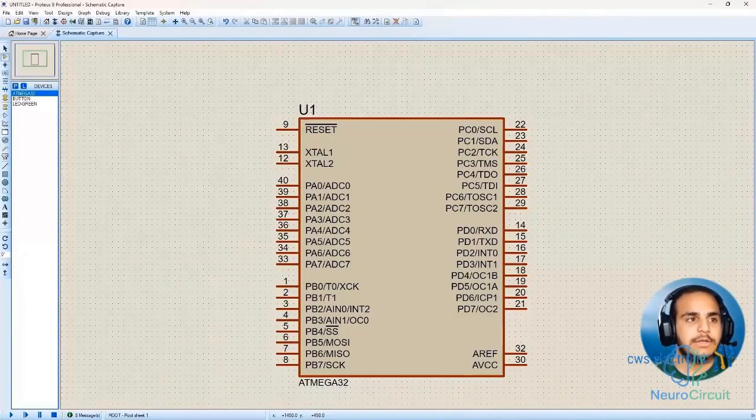Well, the essential point is that in microcontrollers, we inherently have a comprehensive series of input and output ports. That means it categorizes the pins. Now, as you can see here, it says that these 8 pins are port A, these are port B, these are port C, and these are port D. Now, we also have some extra pins that we won't deal with for now. In this categorization, each pin is identified by its port and its number. For example, this pin becomes pin 3 of port A, or this pin becomes pin 0 of port C. And in our programming, we specify them in this way.